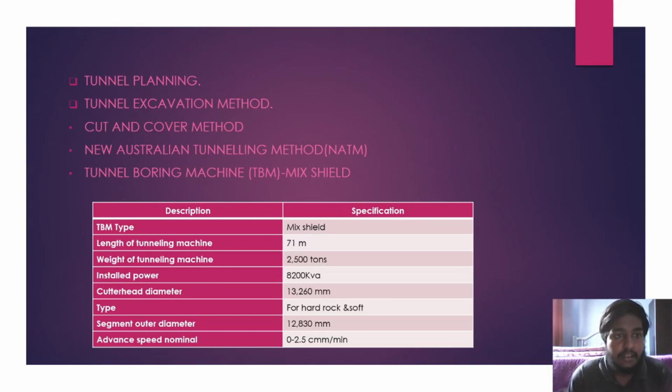So this is quite a difficult ground structure, and deep excavation and underground works in such areas need extreme care. Moreover, rather than being solid, it is filled with cavities. Exposing them during excavation would drain the cavities. Soils are drawn into the cavities and sinkholes appear on the surface. The nature of the soil structure led to the choice of the mixed shield TBM.